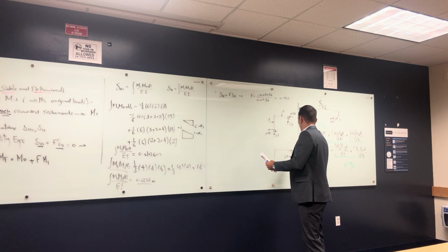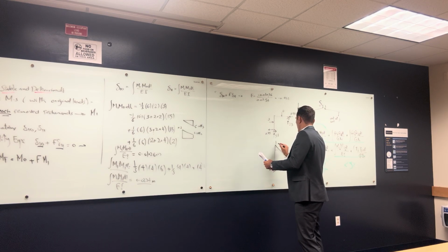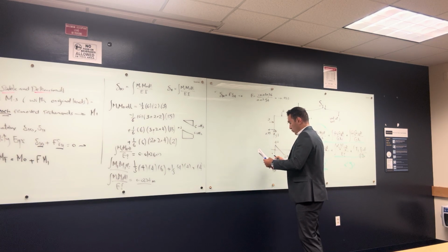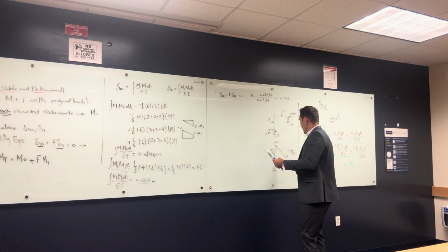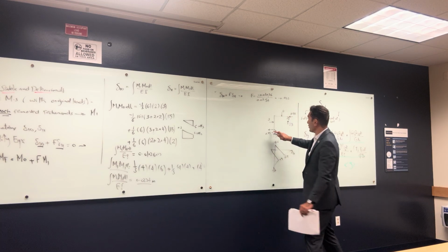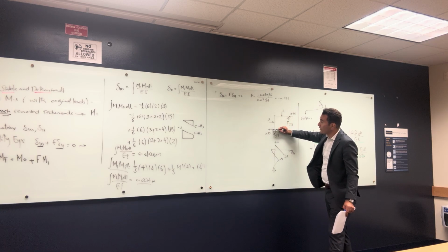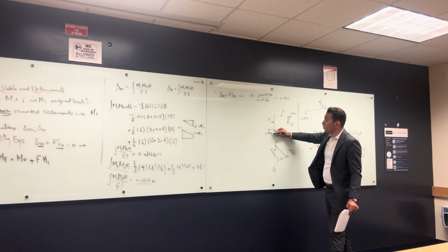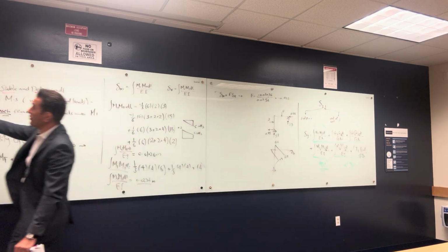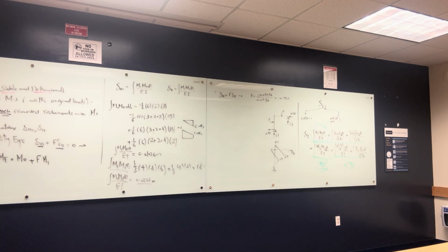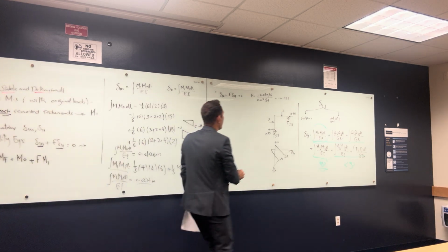And then the moment here is going to be 4.2, and then you're going to get something like this and something like this. This is going to be 0.9, and that makes sense because if you take the moment here before, the reaction here was 0, right now the reaction is 0.45, 0.45 multiplied by 2 is going to give you 0.9, and that makes sense.